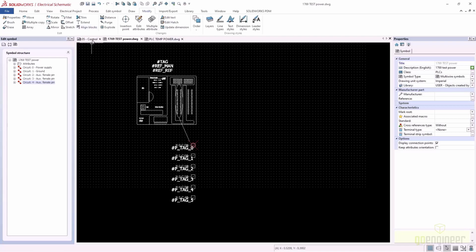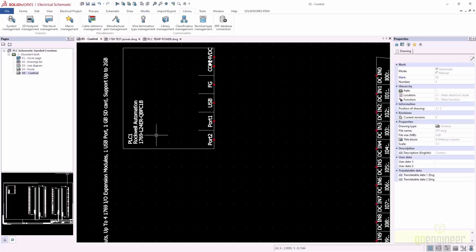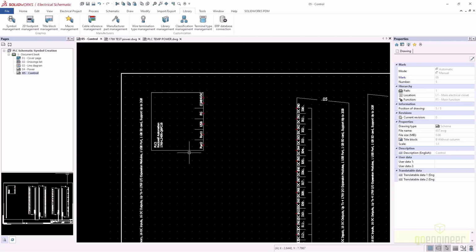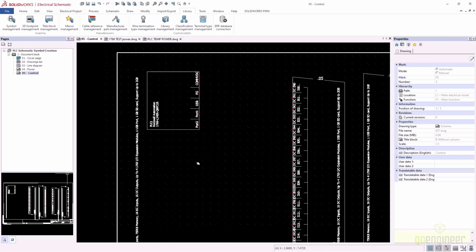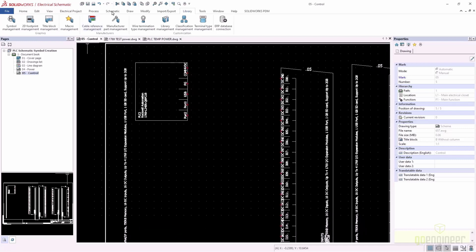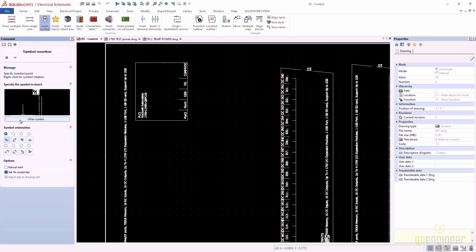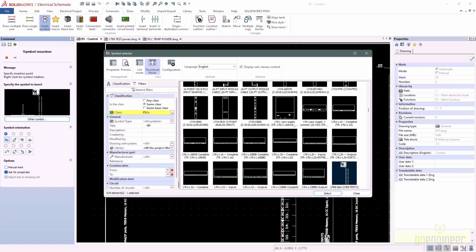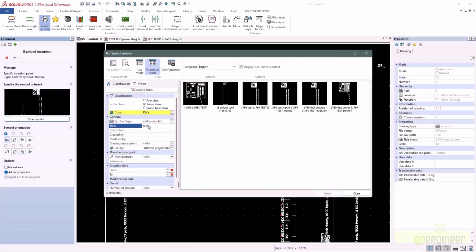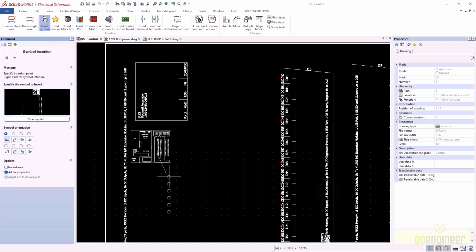And now let's go to our schematic, and I think I'm going to leave this symbol for the moment, just to compare it, make sure I've got everything that I'm wanting here. We'll go ahead and just go up to our schematic tab, and let's say insert symbol. Let's find our test symbol for the power. Takes a minute here to bring that up. We'll go ahead to the title, type in test, grab our power symbol now, select it and place it on the page.